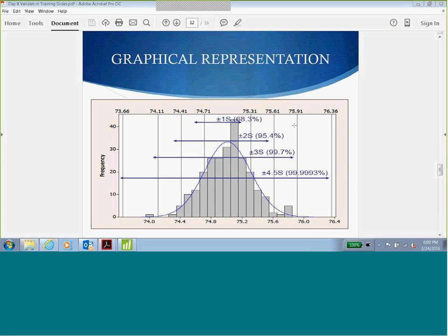Again, it's not going to be true for every manufacturing process. For certain manufacturing processes, you don't care whether the products are within the limit or not, because it might not have a critical impact on the quality of the product. For those processes, you will not follow the same pattern, where you want your results to follow 6 standard deviations. Only those manufacturing processes whose product output is very crucial, which is a CQA parameter, the critical to quality attribute, are the ones for which the company will specifically target 6 standard deviations.